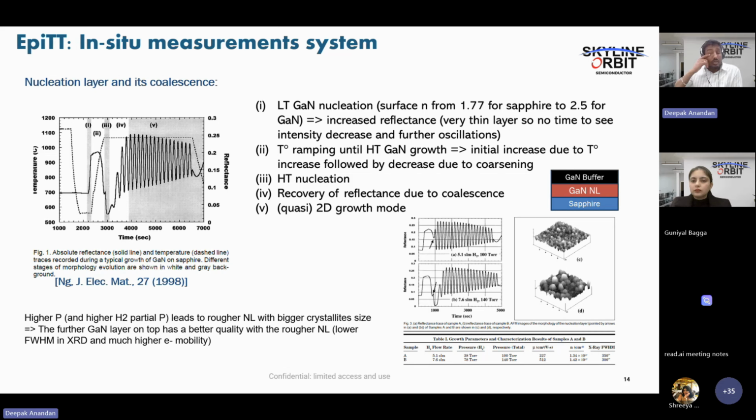So in both cases, if you want to consider or suppress the gate leakage current, it would be good to go with optimizing the gallium nitride metal structure on the p-GaN. That's one thing. The second thing is you need to focus more on the surface passivation. Of course, surface passivation is pretty much the same for D-mode and E-mode.